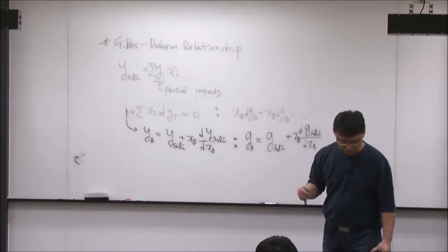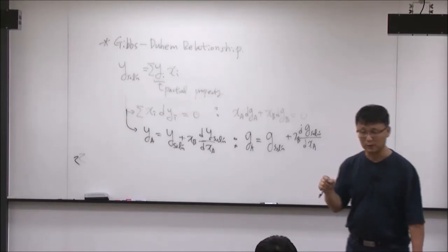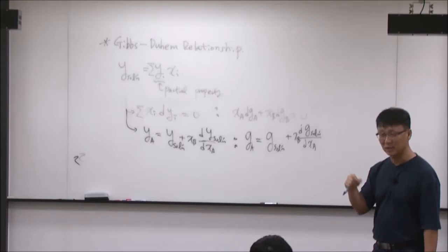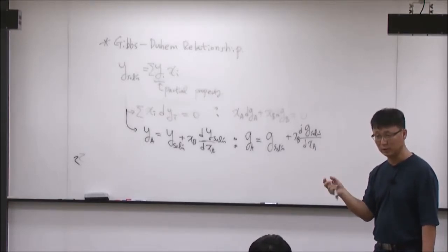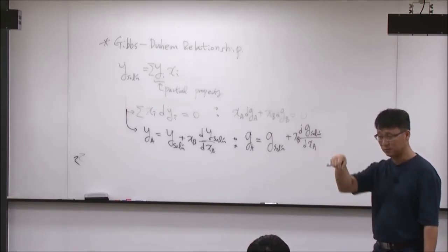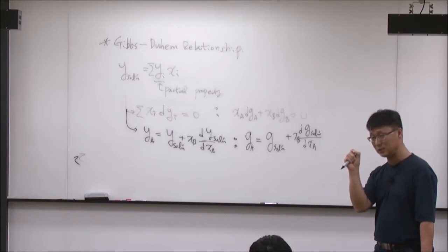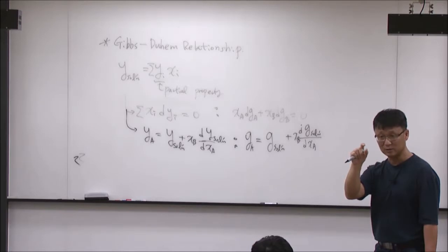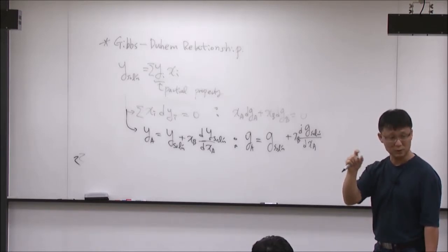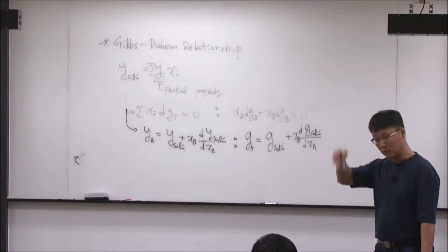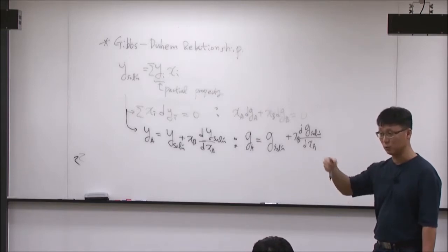Sometimes people are also measuring the enthalpy of mixing, not the total enthalpy of mixing, but the partial enthalpy of mixing. How they measure it is, they make a solution of manganese and iron, 50-50%, and then they add a very small amount of iron into this solution and measure the heat change. By definition, this is the partial enthalpy of mixing of A, the iron. So at a given composition, you do the experiment like this, one by one.